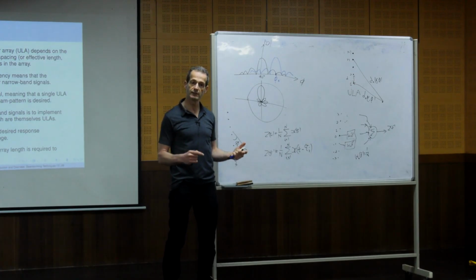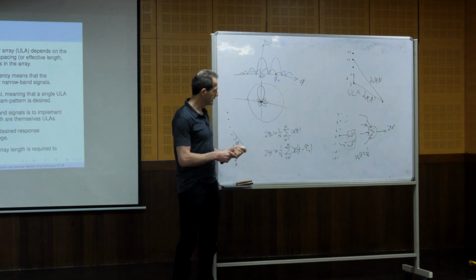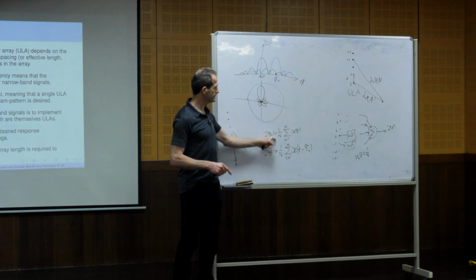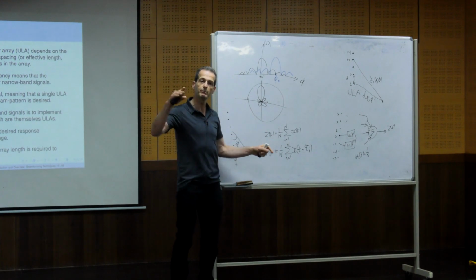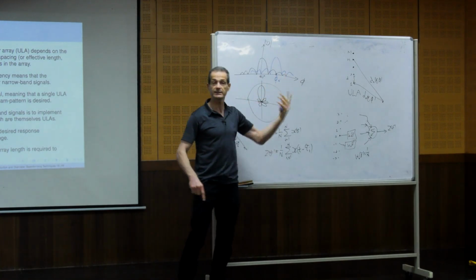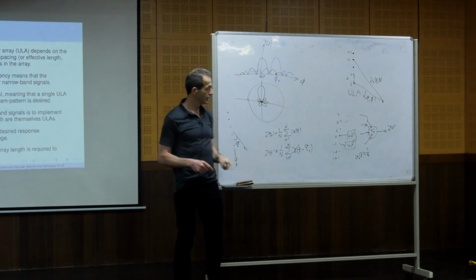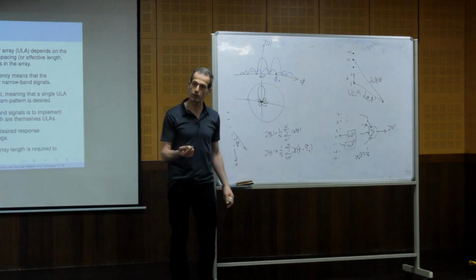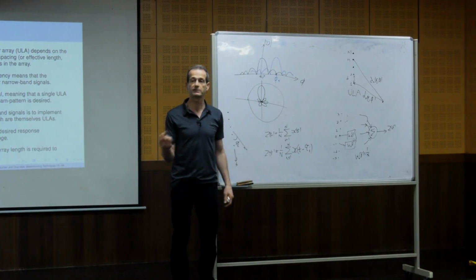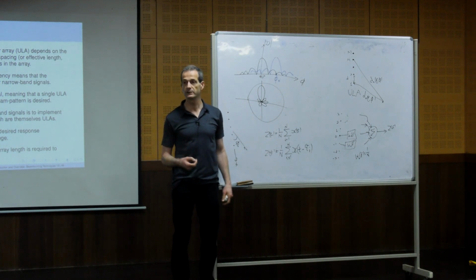But for high frequencies, when the beam is narrow, I will not get it at the output. The gain will be low because the source will maybe be outside of the beam, since the beam is narrow for high frequencies. So the effect of the beamformer will be like a low-pass filter. A low-pass filter distorts the desired signal. So we don't want these